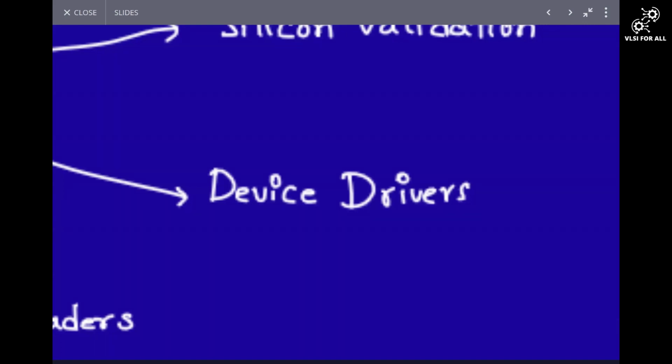In order to calibrate that sensor, we write some values to the registers of that sensor over SPI or I2C, on whichever protocol that sensor works with. Let's say LM75, it works with I2C. Over the I2C, we pass some values to some specific registers which are present within that sensor. Once these registers are programmed, only then can this sensor give you correct values. That's called calibration, right?